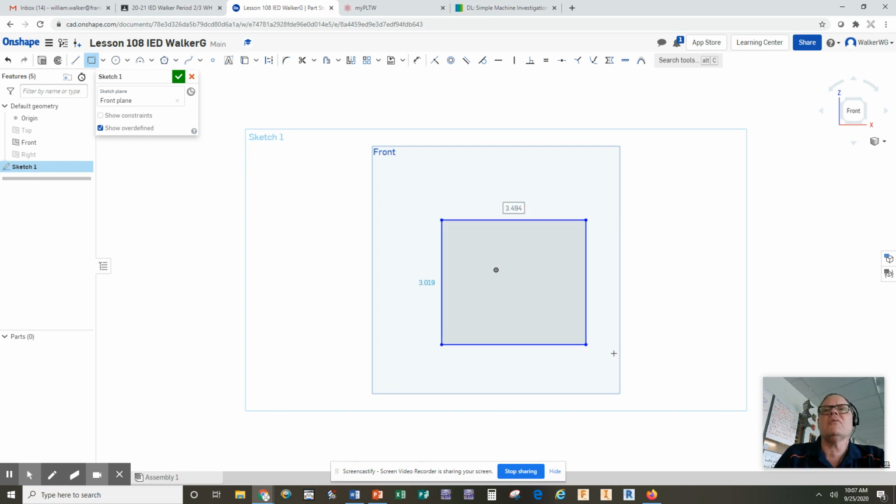Now, you can just leave the default sizes, or you can make exact numbers. Generally in engineering, we want things to be exact dimensions. So let's say I want 3 inches in length. Notice this dimension here has a box around it, meaning you can edit it. So I'm going to just type a 3 on the keyboard and hit enter. And it actually makes that a fixed 3 inches. Over here, now the box is around this number. So I'm going to type in a 2 and enter and make that a 2-inch box. So now I have a rectangle that's 3 by 2. Not really necessary that it be centered on the plane. I have a 3 by 2 block, exact dimensions, right? So now that I'm done drawing my sketch, my 2D sketch is complete, it's dimensioned.